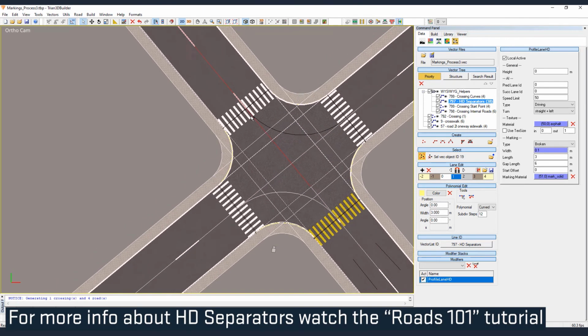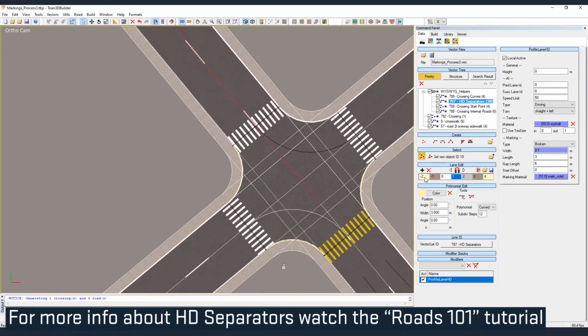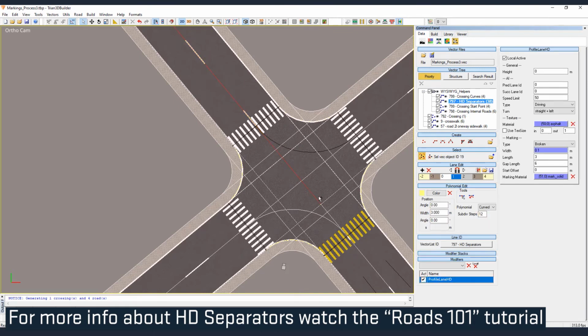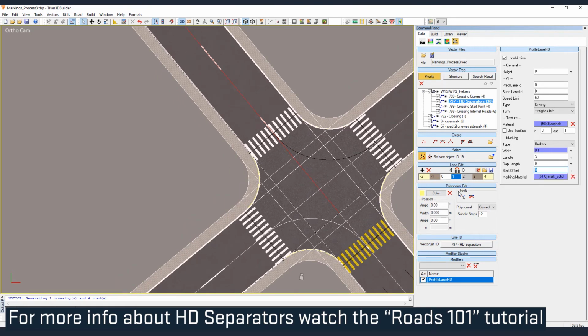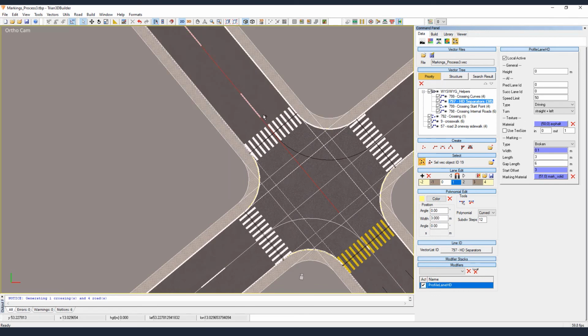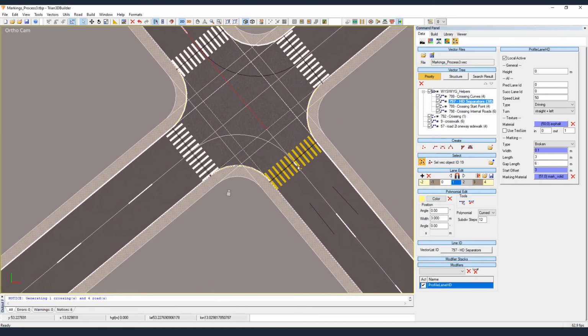So select that road in element mode first. We see the direction, it starts from here, so maybe just an offset will work for that. Let's try it. A 3-meter offset, and yeah, that worked. It was easier to see because the line started there.